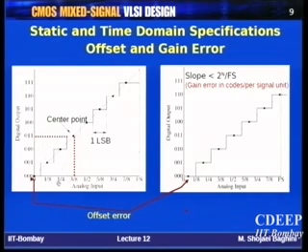So suppose you have a comparator which has some offset at the input. Therefore, if you apply a reference to one of the inputs, the other input is applied and it is your signal. So the output of the comparator will toggle only if your input is your reference value plus V offset plus some smaller value, which is the resolution of the comparator.